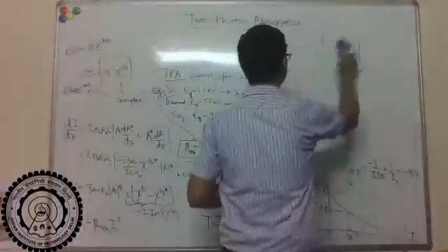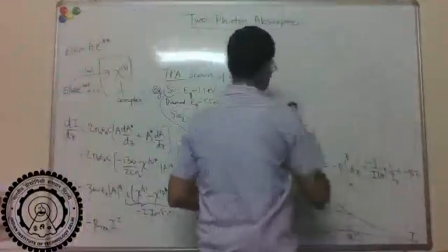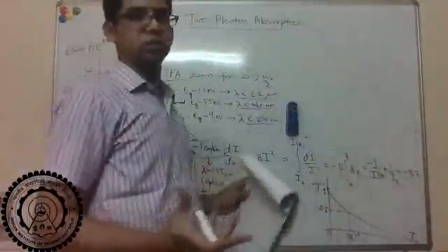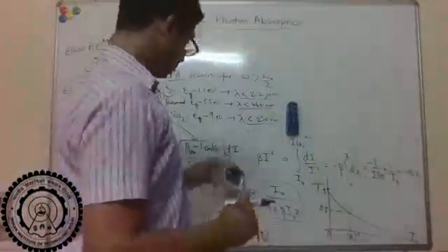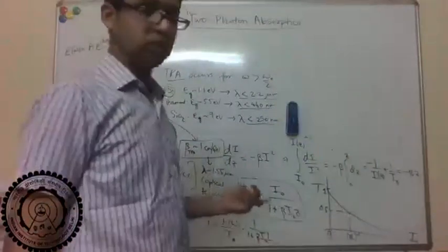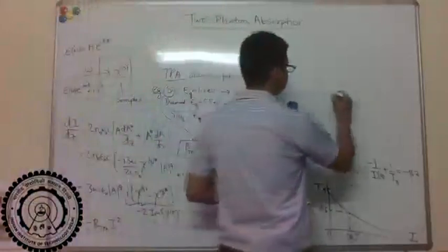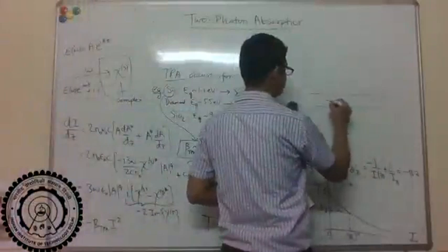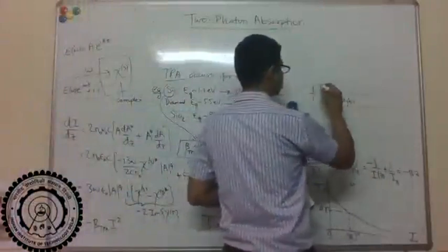So lithography is when you want to make some very small structures, right? So we make electronic components which are sub-micron and down to like tens of nanometers scale. We now also want to make optical waveguides which are, let's say, sub-micron. Right, and typically what is done is you take some wafer, some, let's say, silicon wafer or whatever you have. Then you coat some resist.